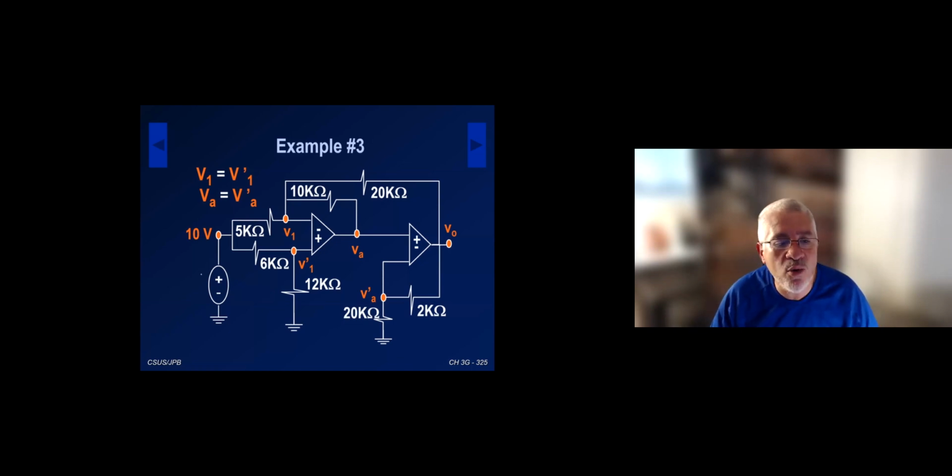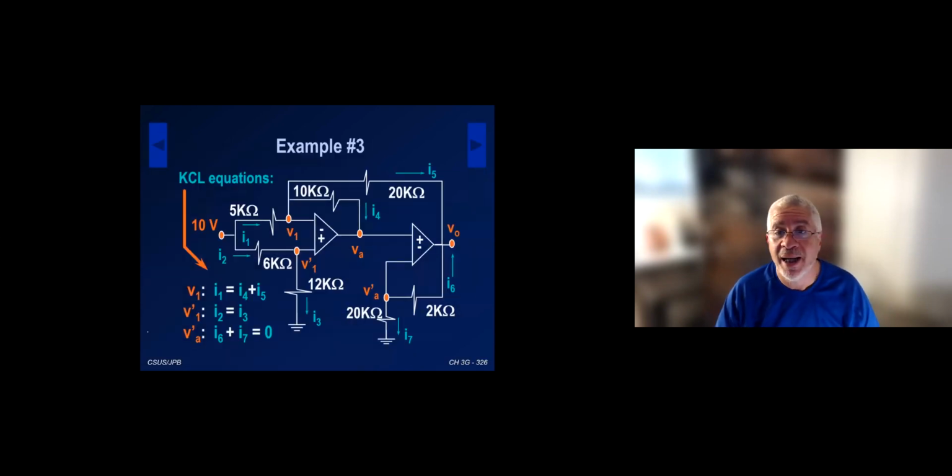And then you see me moving the 10 volt to that node. That's my source equation. The 10 volt moves into that node because the voltage source is connected to ground on the negative terminal. Okay, so I'm going to put current on my resistors. I changed the picture a little bit so I can have room to work here, because I had no room given that the circuit is so big.